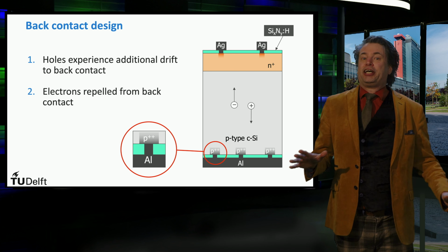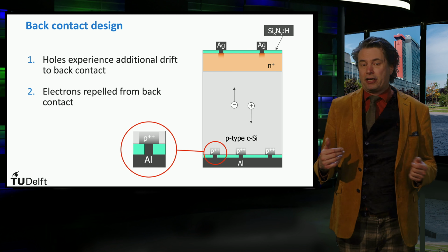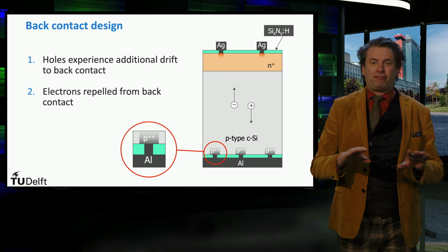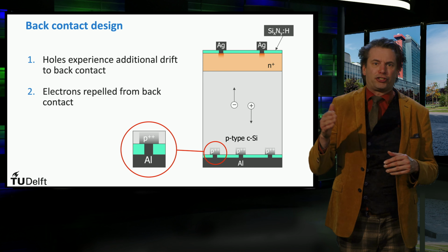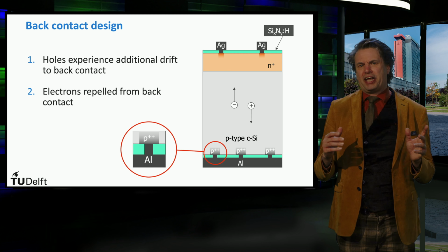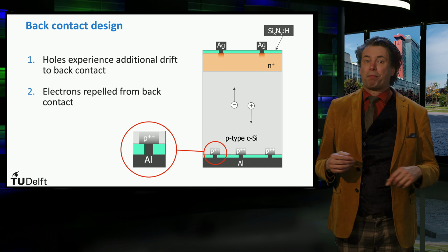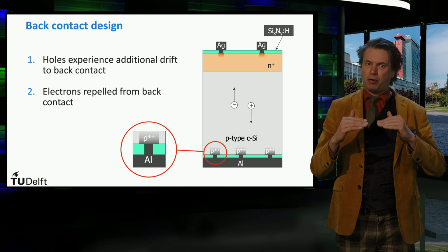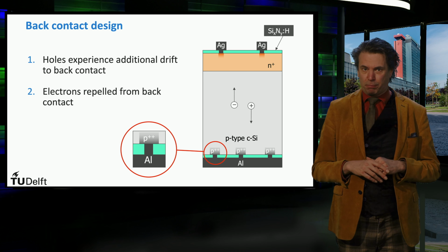First, we can reduce again the area between the metal contact and the semiconductor. We can make point contacts. The rest of the rear surface is then passivated by an insulating passivation layer, similar as we have discussed for the cases of the emitter front surface. The loss mechanism of recombination of electrons at the back contact can be further reduced by a so-called back surface field. A higher p-doped region is placed above the point contacts at the rear surface indicated by P++.